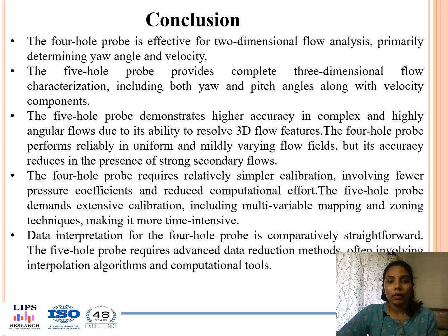It gives high accuracy for angular as well as three-dimensional flows because it can resolve flow variations in multiple planes. Now, looking at the calibration requirements, the four-hole flow analyzer requires simpler calibration methods compared to the five-hole flow analyzer. As I've told, the calibration process is extensively larger compared with the four-hole flow analyzer.